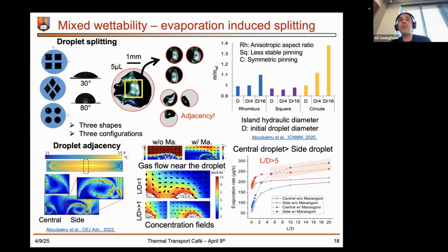So for wetting liquids, what I would suggest is larger pitch sizes, because the bubbles are larger. The idea of having adjacent islands is not to increase the coalescence-induced bubble departure. It is more to provide some nucleation sites for the inception of boiling, and to have it under control rather than the formation of a larger vapor column or vapor slug in the channel.